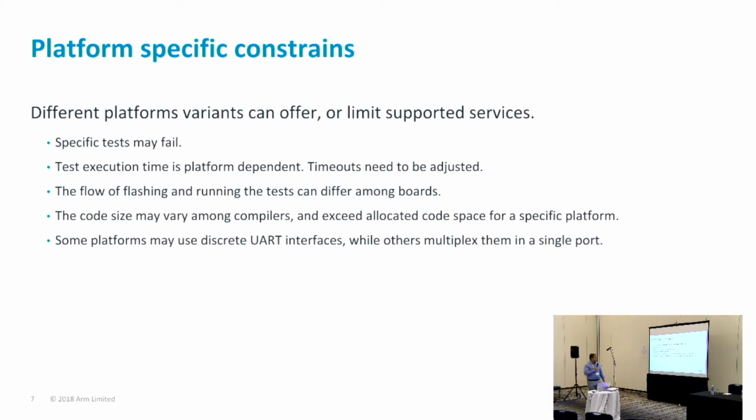So testing has a lot of platform-specific constraints which we need to take into account. Aside from different hardware variants and existing or non-existing optional hardware contained in a platform, some tests might fail, some service-related tests might fail. But also, platform execution time is board dependent. If you have a platform booting from RAM and a platform booting from QSPI with execute in place, timeouts might be triggered. You need to take that into account.